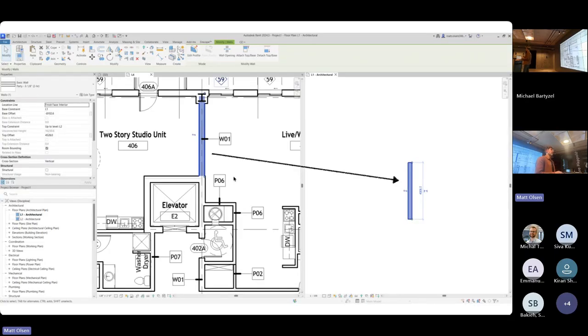Issue number one is that materials are very much locked into models, which I'll explain. Unlike component families like doors, which you can save out of projects as an RFA file, or system families like walls, which you can copy and paste between models in the same session, transferring materials across models and families is a bit more cumbersome. It's not easy for an architect to just grab a material they used on a previous project to use on a new one. There are two main ways that you can transfer a material between projects.